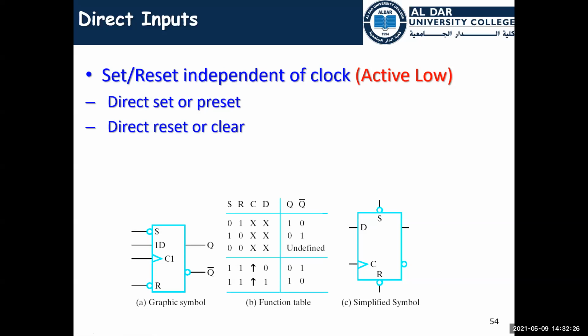As you do in the computer, if you press the reset button, it is going to close the computer and reset it again. This is the same concept here. We have the set and reset. They are active low, meaning that at 0 it is going to set the D flip-flop, and here at 0 it is going to reset the flip-flop.